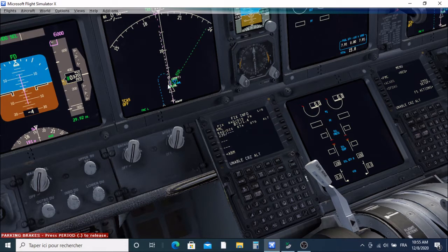So once we took off, and once we reach 6,000 feet, we are going to turn to the crosswind, so west basically, and once we reach this radial, we will turn to the downwind. And same, the end of the downwind will be shown by the radial 340, and the end of the base will be shown with radial 355. And after this, we will intercept the ILS 19 left. So okay, everything is done for this. I will go back to the takeoff page.